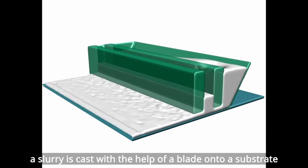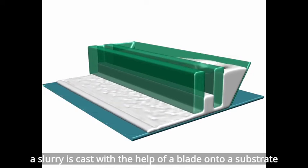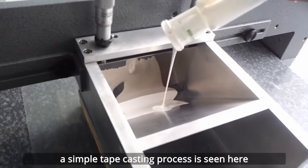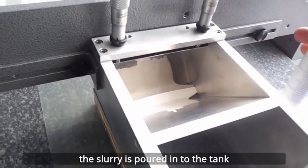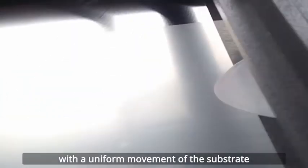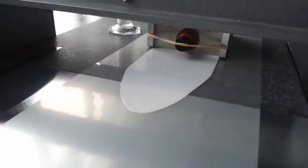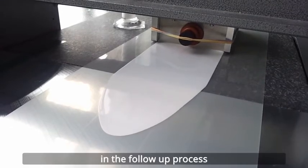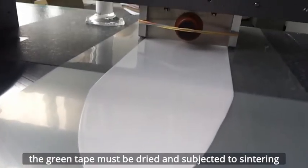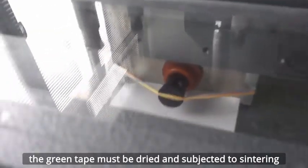A slurry is cast with the help of a blade onto a substrate. A simple tape casting process is seen here. The slurry is poured into the tank. With a uniform movement of the substrate, one tape casted thin layer is formed. In the follow-up process, the green tape must be dried and subjected to sintering.